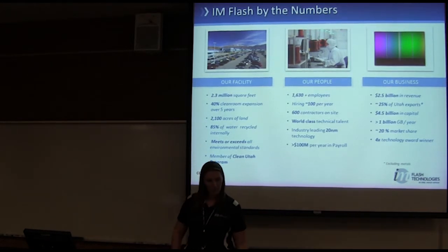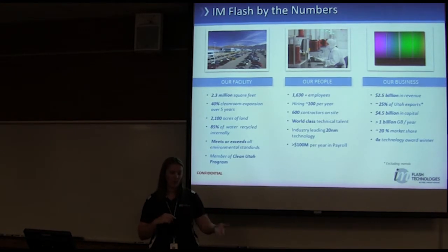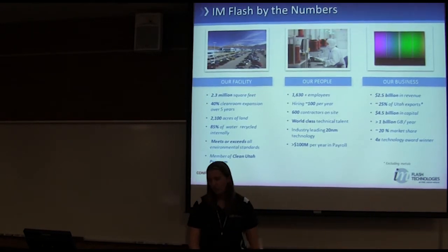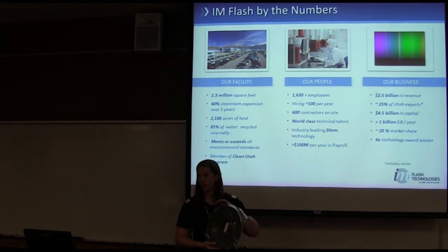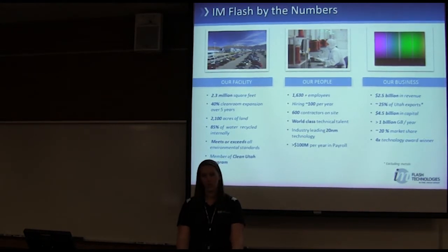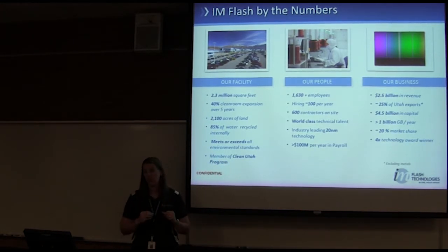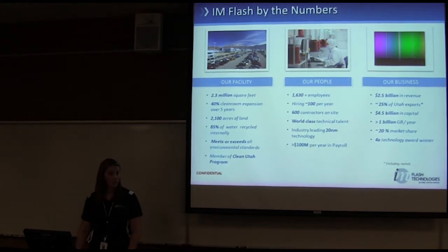And it used to be what, like 70 millimeters, or what was the old technology? You know, it keeps changing. 2-inch wafers, 3-inch wafers, 6-inch wafers, 8-inch wafers, to 12-inch wafers. There's actually companies out there looking at 15-inch wafers. The costly part about changing wafer size is you have to change all your tooling, right? Because the tools are expecting a specific size of wafer to pick up and handle and sit on a chuck within a tool. So when you hear about fabs going from an 8-inch wafer to a 12-inch wafer, they're dumping a lot of money into their tools to make them capable of manufacturing larger size wafers.